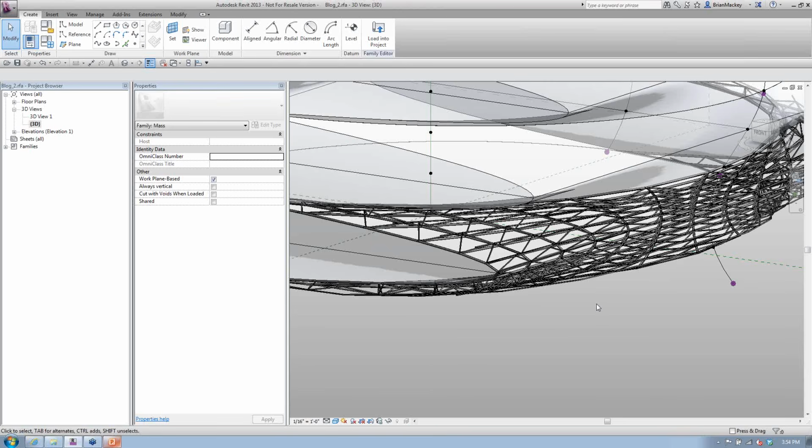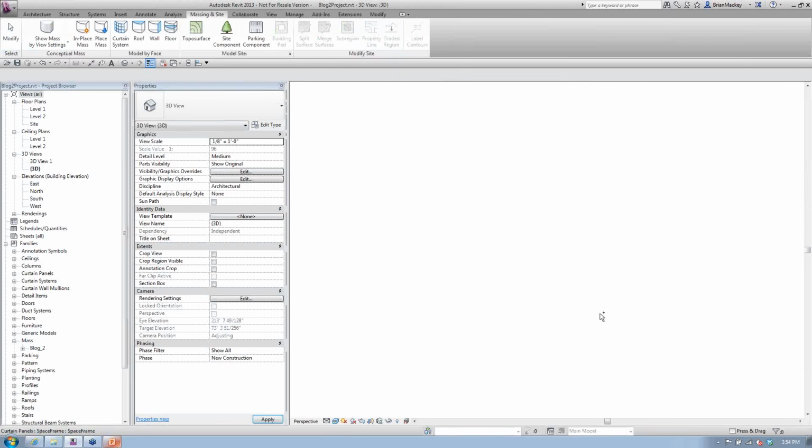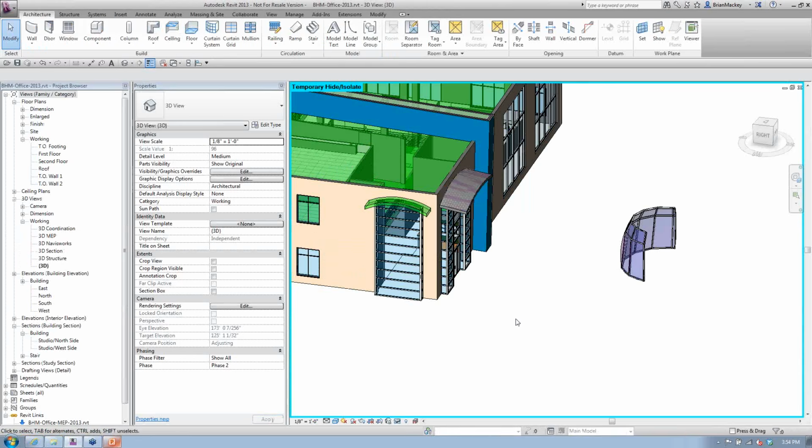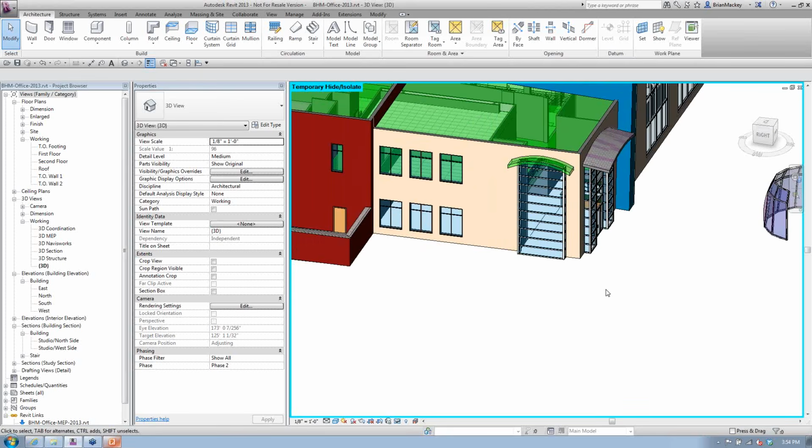So hopefully you all saw how we went through, created just a line, sloped the line, applied a wall to the face of those lines, did a mass. Another one that I get asked a lot, and I'll get back into that simple project maybe, should hit close windows. Another one that I get asked a lot is, how do I do a sloping stone column or a tapered stone column? It's going to basically be the same thing.